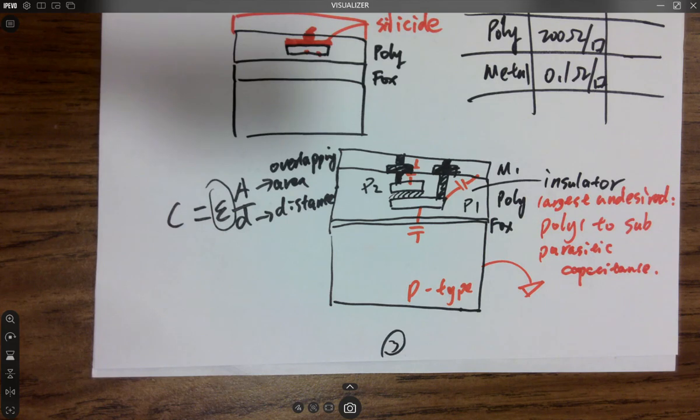So you design the RTL from the front end designer and convert it into layout, and then the rest of the time is just for timing. And the software can include parasitics? Yes, that's why it's reporting you the timing, because it's able to detect that, even though it's not super accurate sometimes. But that's why the Cadence tools are so expensive, because they can do all this analysis, and the open source tools cannot. That's another interesting thing to talk about. There are a lot of efforts.